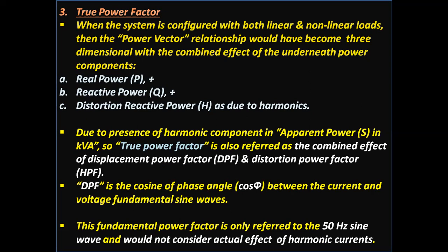That is P, Q, and H. Due to the presence of harmonic components in apparent power in kVA, true power factor is also referred to as the combined effect of displacement power factor and distortion power factor. That is represented as harmonic power factor, that is HPF.